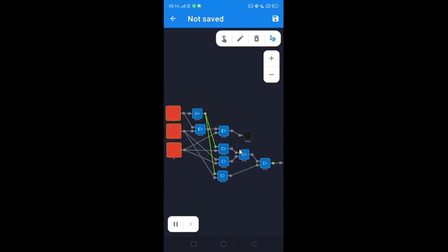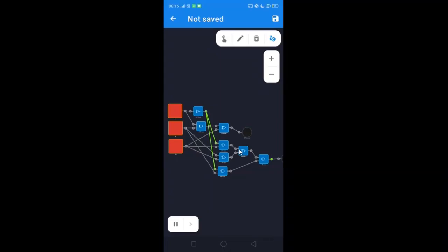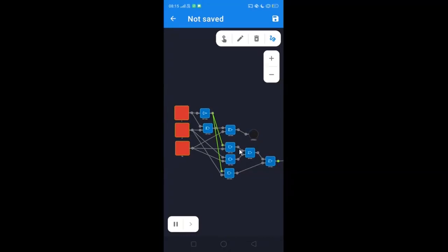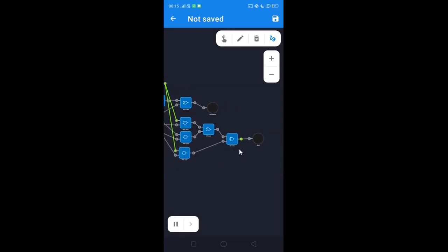Now after making the whole circuit diagram, the next step is we should verify whether our circuit is correct or not. How can we verify our circuit? By using the truth table of the given circuit. You already know the truth table of the full subtractor. So let's try to verify here. Here all inputs are 0. If all inputs are 0, then borrow and difference will be 0 0.